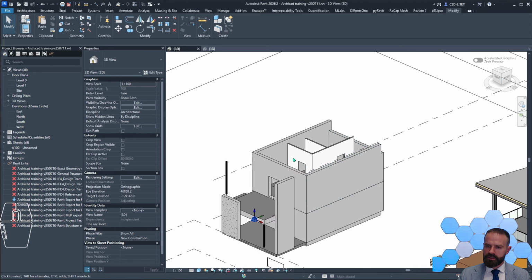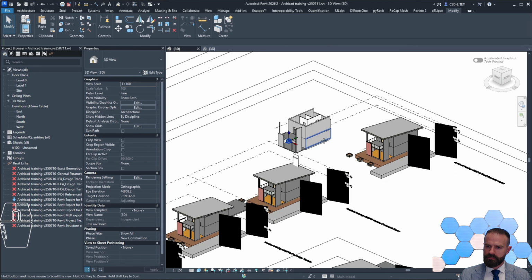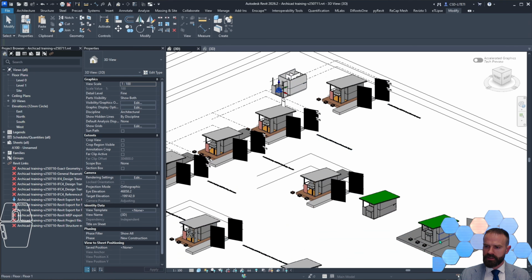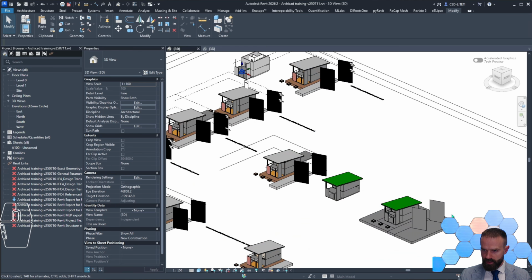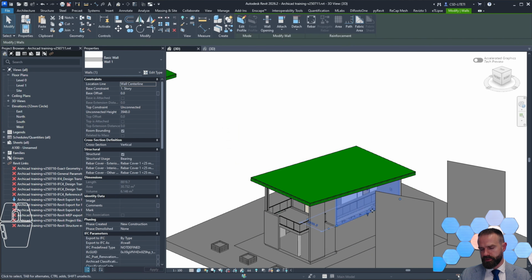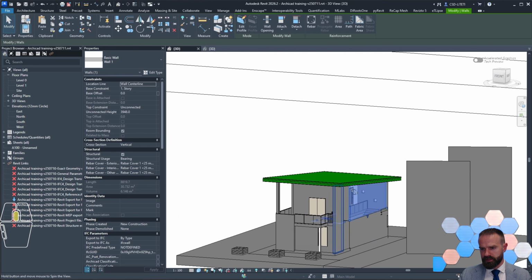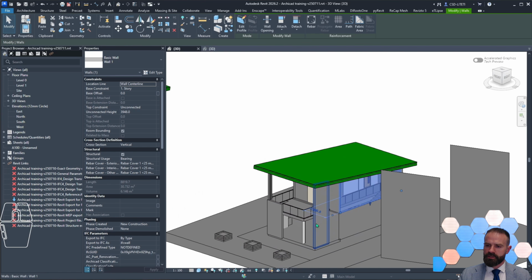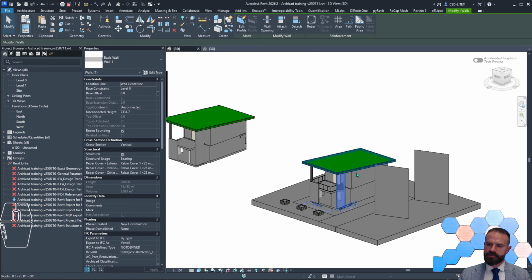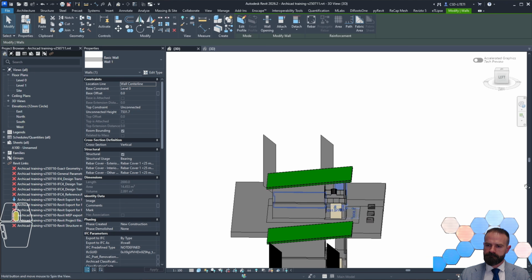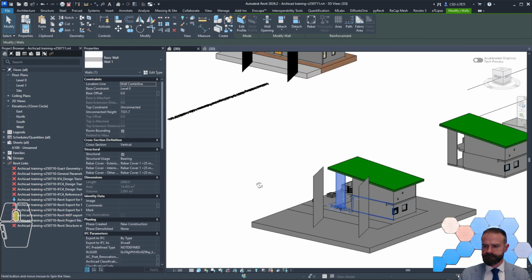Roof is not coming, so to bring the roof and all the cuts of the walls, you should implement Open IFC file, and you will get full geometry of all bearing elements, and you can modify, adapt them specifically for structure models.